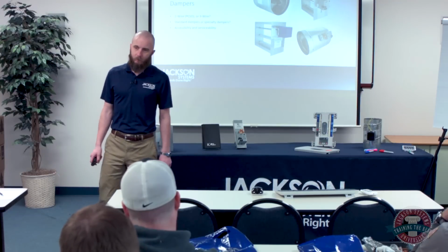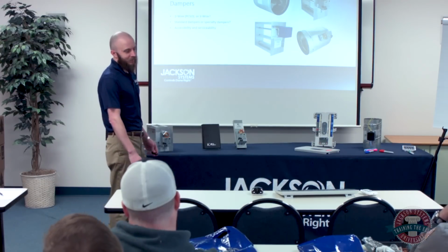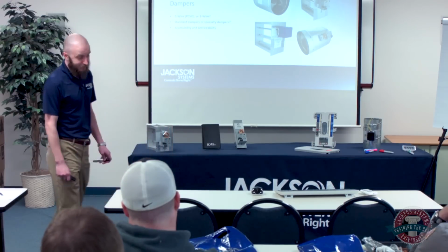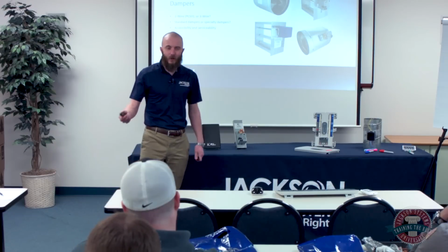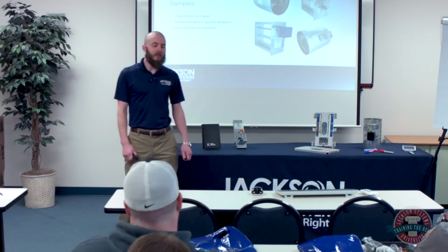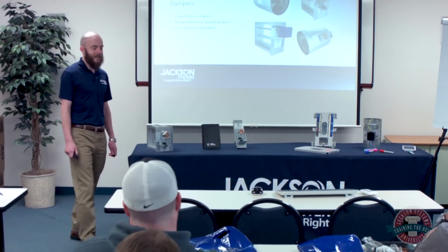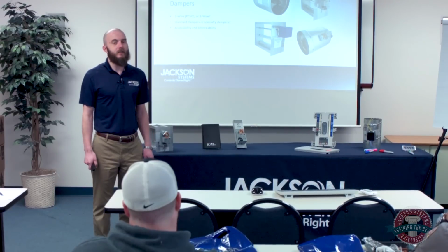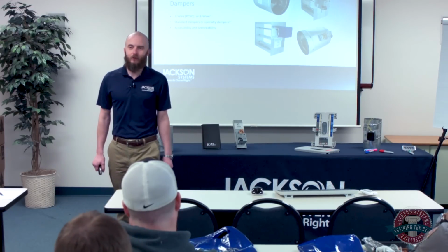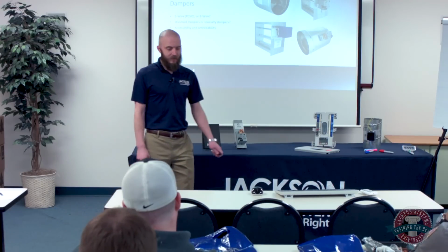One big thing there, the third bullet point, is a big one: accessibility and serviceability. Please, please, please, for the love of God, do not install zone dampers in a place where no one could ever get to them again, if at all possible, because it could be you. Obviously, you can't control what the homeowner is going to do after you leave, so if you install some dampers in a basement and they decide to finish their basement and hide all of their dampers behind drywall, there's nothing you can do about that. But I would highly encourage you to always put them in locations where they are as accessible and as serviceable as possible. The dampers we carry all have a 10-year warranty, which is a pretty good long time, but it is, as you may have noticed, not forever. Eventually, those dampers are going to need to be checked out, serviced, or replaced. So don't hide them in places where they can't be gotten to.